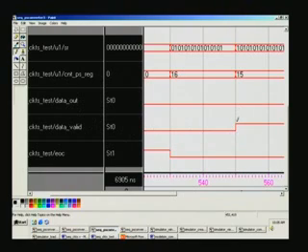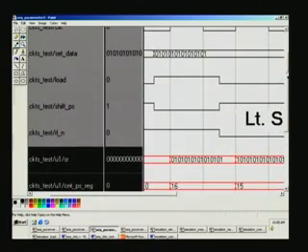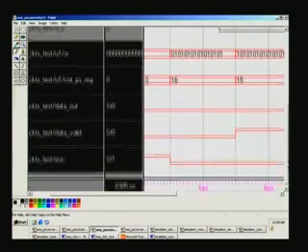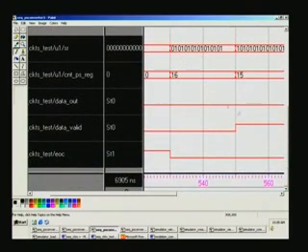So it will have to be asserted here the moment data starts flowing out, and once again the parallel to serial conversion takes place, but this time it is a left shift, as is here. See, it was 1 here for the earlier thing, it becomes 0 here, implying it is a left shift. So if it is a left shift, 0 must go through first here. That's where data out is, so 0 is there, and data valid is asserted here,